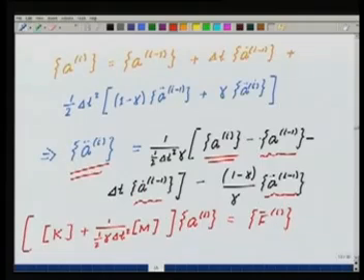Okay. So that is a simple algebraic job that one has to do. For example, it will be plus 1 by half delta t squared gamma into m operating on a at I minus 1, plus 1 by half delta t gamma into m operating on a dot at I minus 1, plus m times 1 minus gamma by gamma operating on a double dot at I minus 1. Okay. So this will give me the load vector, and then I invert this matrix. This matrix I'll call k bar.